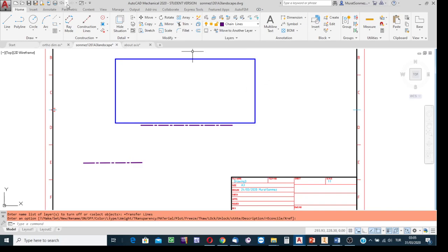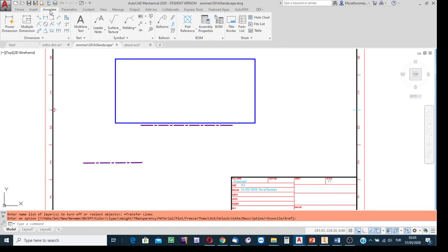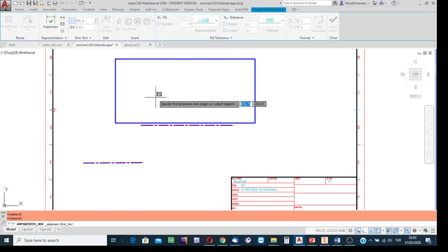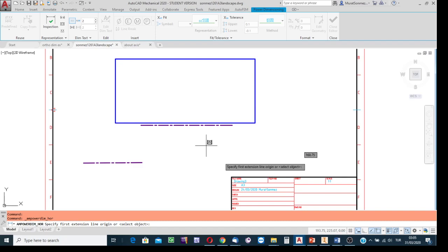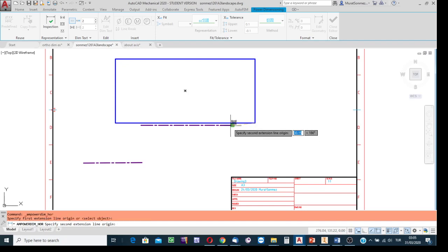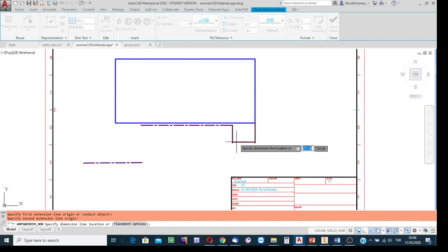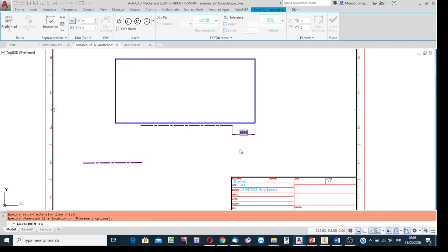And then show the dimensions. Under Annotation, click on the dimension indication button. Later, I will study dimensioning format and the associated things in the CAD environment more deeply, but here, to complete my demo. Using the snap facility, indicate this point as the reference, the starting point of the chain line, and then move the cursor away and click. Yes, 30 millimeters. Press enter, and then continue.